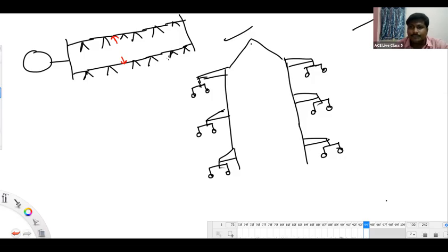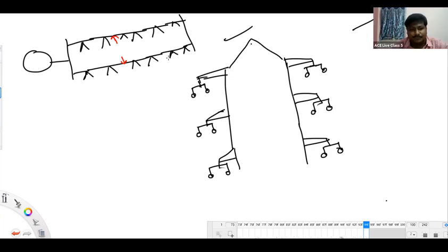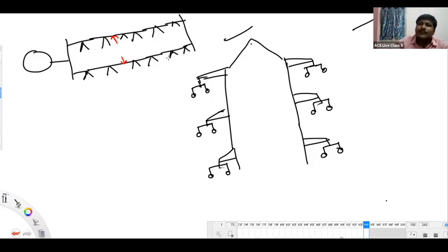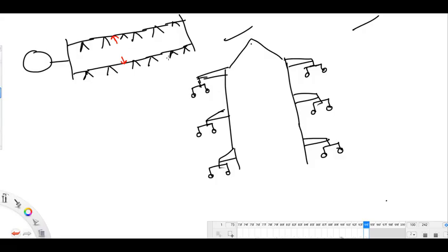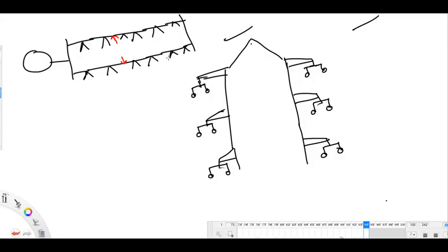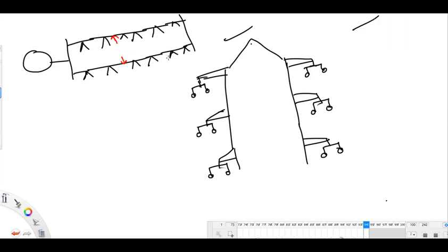There will be one more line, sir, on top of this tower. What is that? That's the ground wire, or earth wire, for lightning protection. Whenever a lightning strike occurs, to avoid the lightning stroke falling on the power conductor directly, that line will absorb it. It is a completely useless wire in steady state operation, but it is protection for the power network from lightning strokes. Okay, thank you, sir.